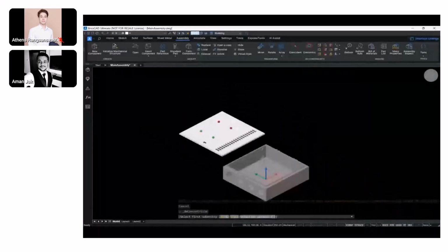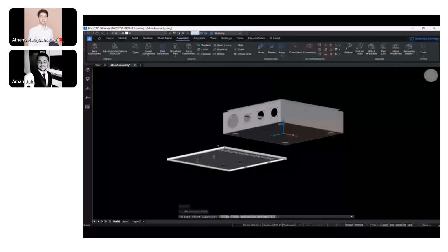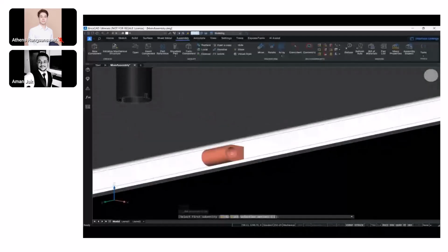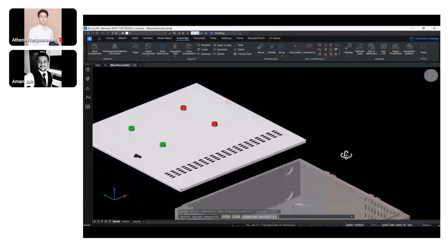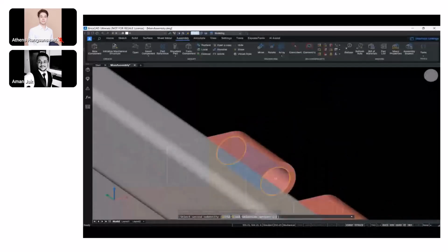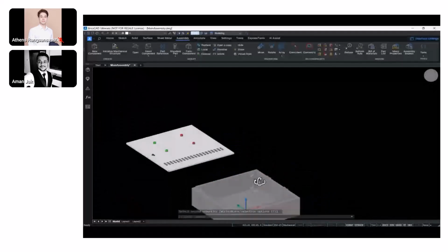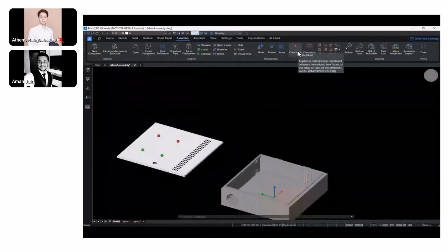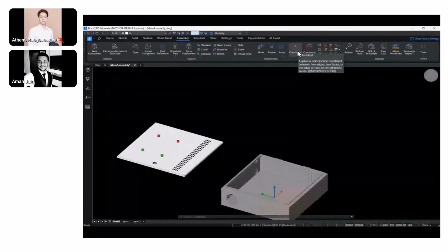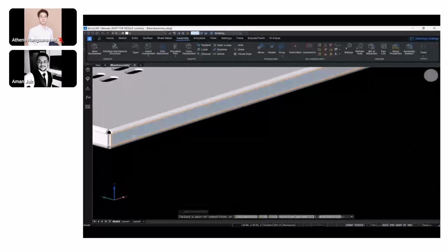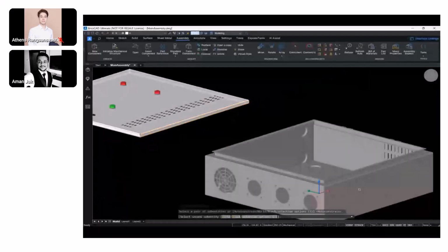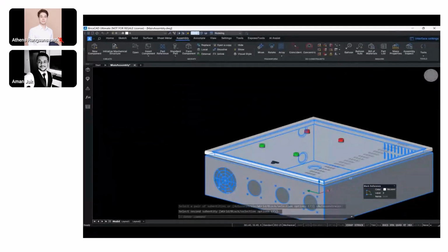So for me, now it really becomes easy to apply the constraints. Had it been placed vice versa or in the opposite direction, it could have still worked, but it's a bit more difficult for the software to understand how the geometry needs to rotate or what the design intent is. So it's better we keep it constraint ready so that it helps us constrain it very easily. So it's just two constraints that I've applied, and my entire geometry is now constrained.